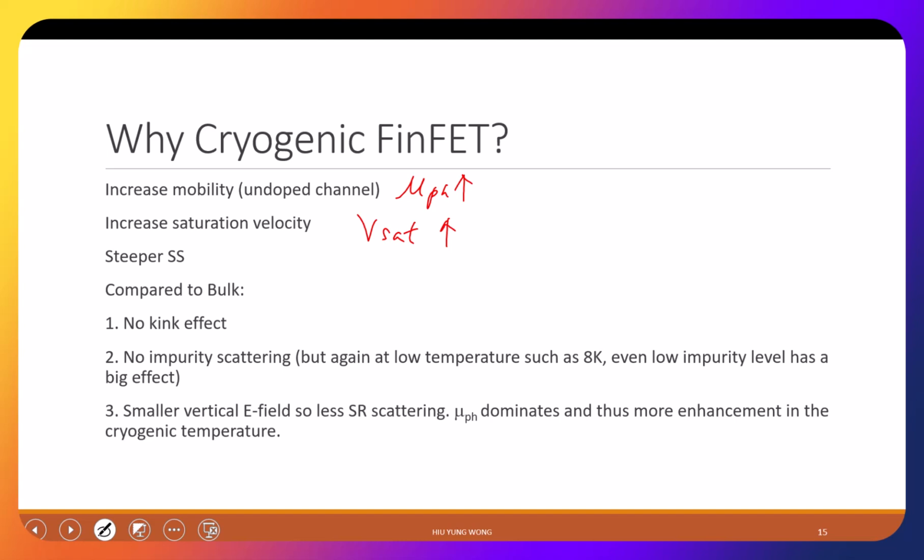Now that's one thing though. I talked about undoped channel. I just want to emphasize one more time. This is something you should know very well. In a typical MOSFET, maybe you have 1E21 or 1E20 of source-drain doping, and then here maybe 1E18. If you go to 45 nanometer, right? The one we're doing, 65 nanometer, is like 5.5E17, right? Yeah. But in FinFET,